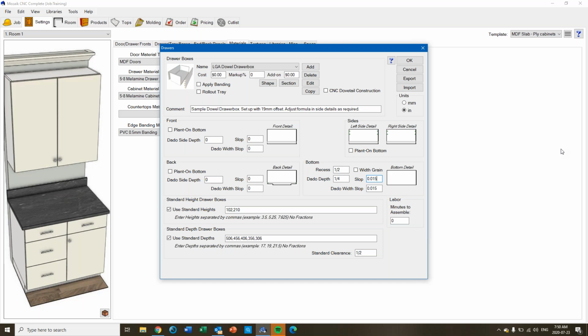Yeah, because every time I do my drawers, I have to run it through the table saw because it's too tight. Goes in, it's perfect, right? But then you start getting a problem. So you do the slop on the width, and this one you said on the depth as well. Yeah, you want it to be a little deeper for glue, and sometimes when you cut something, it might fur up a little bit. Typically you'll do it on the depth too.